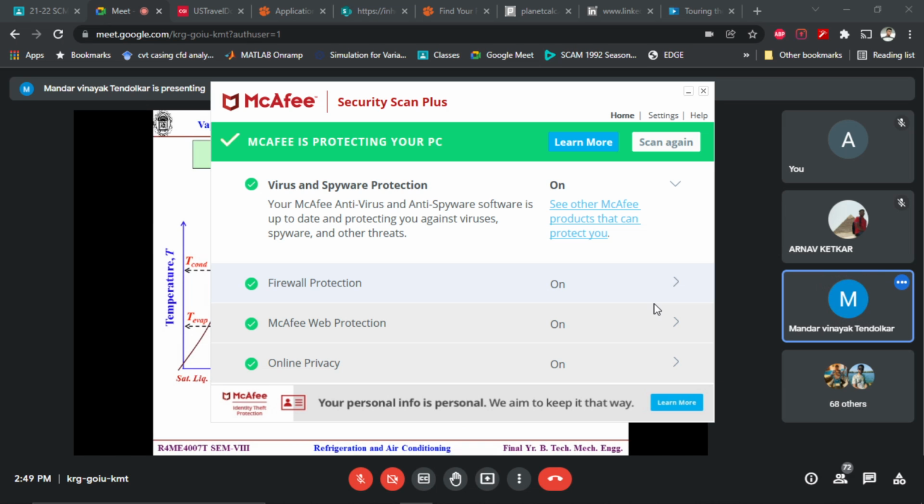Okay. Now Q rejected in the Carnot cycle and Q rejected in the VCC cycle. What is that area? Only this much difference. The Carnot cycle is this. The VCC cycle is this. So how much is the difference? 2 dash, 2 double dash, 2, 2 dash. So this is a triangular part. Do you agree? Heat rejected is in the condenser. Yes.